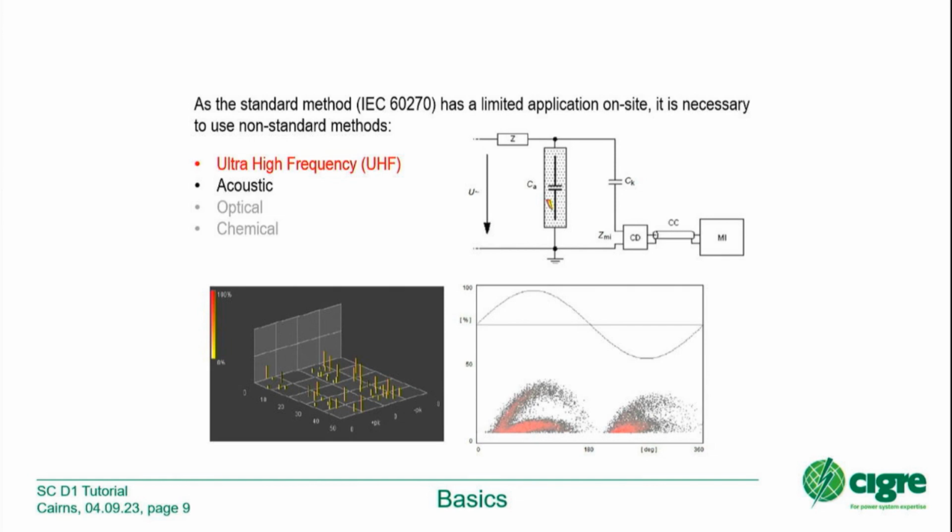But of course, I will not say call me, you can call him. No, if you have, you have to be independent today. If you have in service more than 1 defect, then you have to sort it out, of course. And this can be done by maybe switching operation. Disconnect 1 part of the GIS and maybe by chance 1 PD defect disappears.